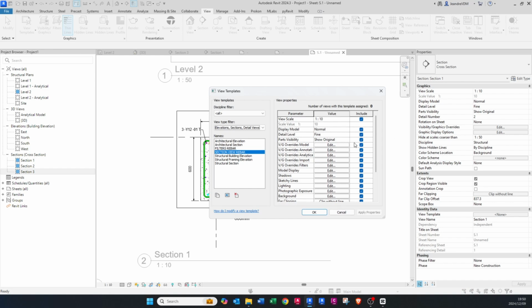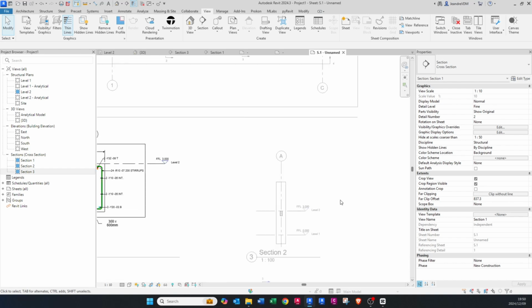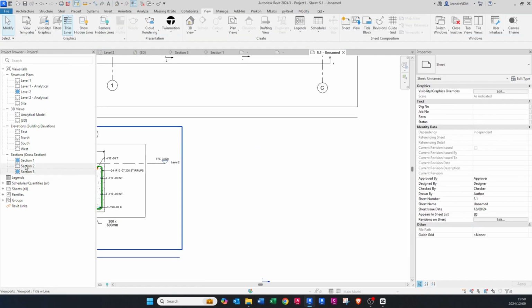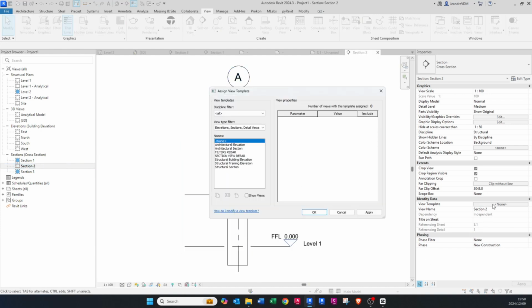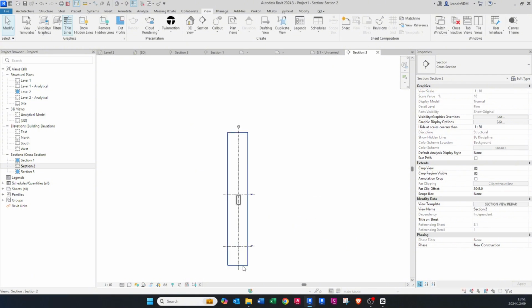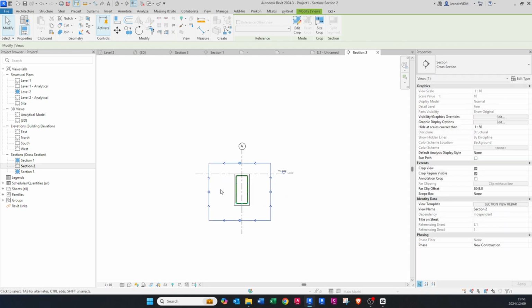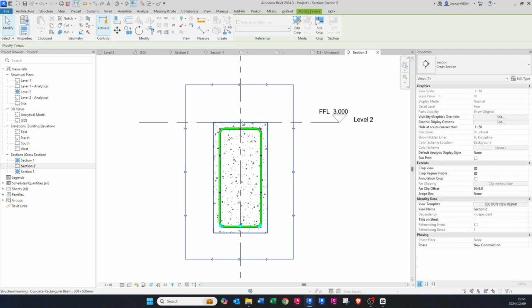And I'm going to leave all of this ticked. Okay. Now, I'm just going to delete this section and I'm going to go into the section view. So now if I go here to none and I say section view rebar, I want that template and I say okay. It already puts it to the scale that previous rebar is, and it also color codes it for me.